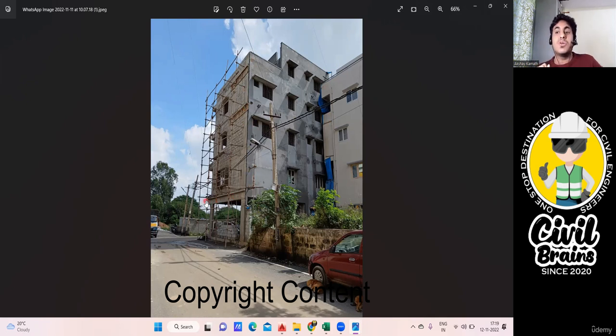Whereas in the brickwork, what I used to tell, I used to tell take from the inside of the column, right? If my column was here, I used to take from this end to this end. So from inner to inner, it was there. But in plastering, complete external thing, everything will come outer to outer. That is the first thing you need to take care of. Other than that, the deduction part and all I will explain in the later part. Now it's understood, no? So I'll directly go back to the drawing now.